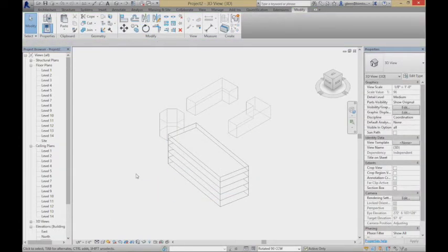Okay, and this is going to test the effect of the difference between having all that long flat face facing the south versus the east-west. You'll find that's actually a very significant kind of change. In climates where we want to collect a lot of heat, we'll often face the long face to the south because we want to capture a lot of sun during the winter and heat things up on the southern side.